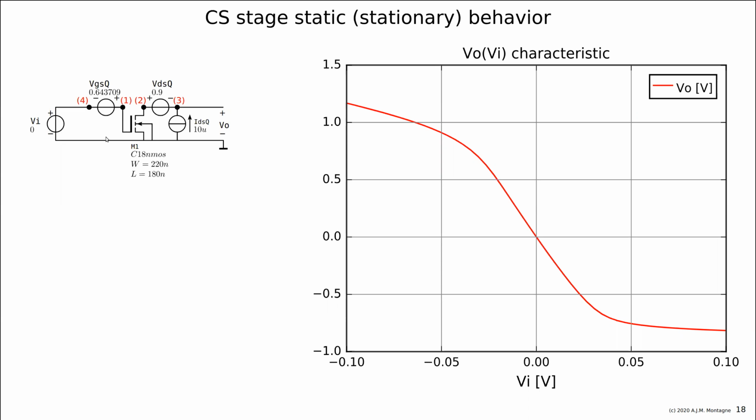So you know this voltage change here would, let's say, cause, because of the biasing, a current flow in the FET, changing the output voltage. And if the output impedance was infinite, then it would be a straight line, exactly vertical through the origin, but the output impedance of the MOS is not infinite.